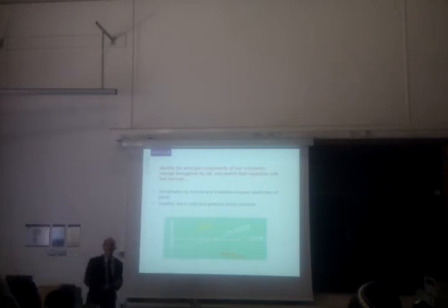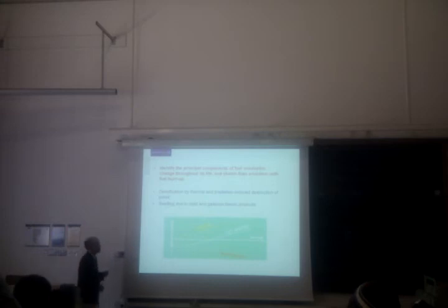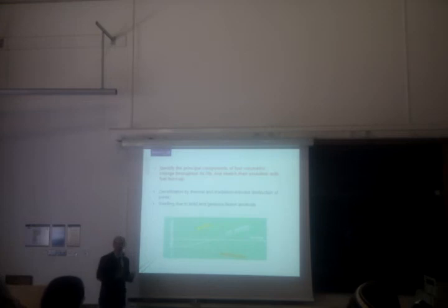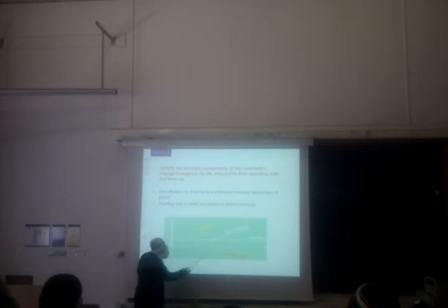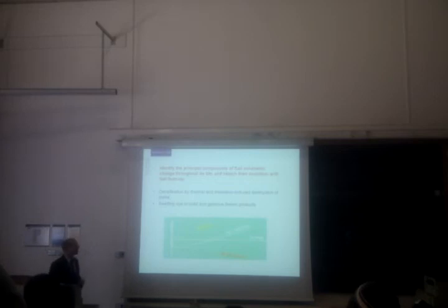You can't just keep on getting denser and denser. You can't, yeah. There's only 5% porosity in there anyway, so we can't carry on densifying it. Eventually, we will get 100% dense. What actually happens is that we fairly quickly get rid of the population of very small pores, typically 5 microns or less, and we're left eventually with a structure of fairly large spherical stable pores, typically 10–15 microns or so